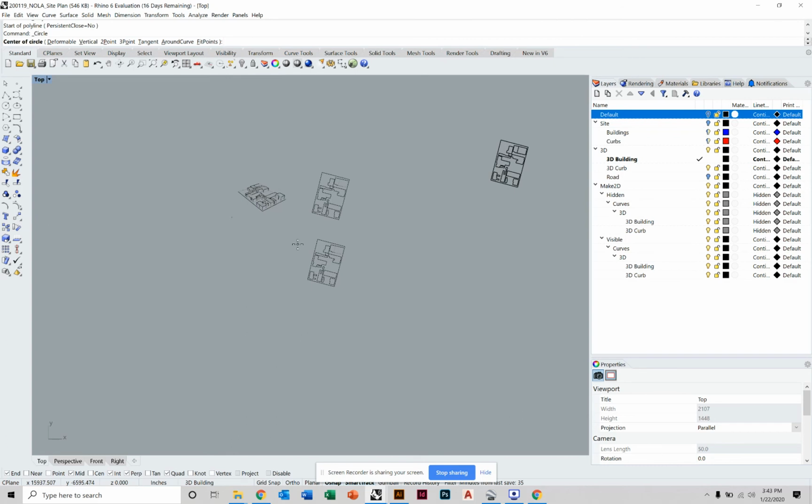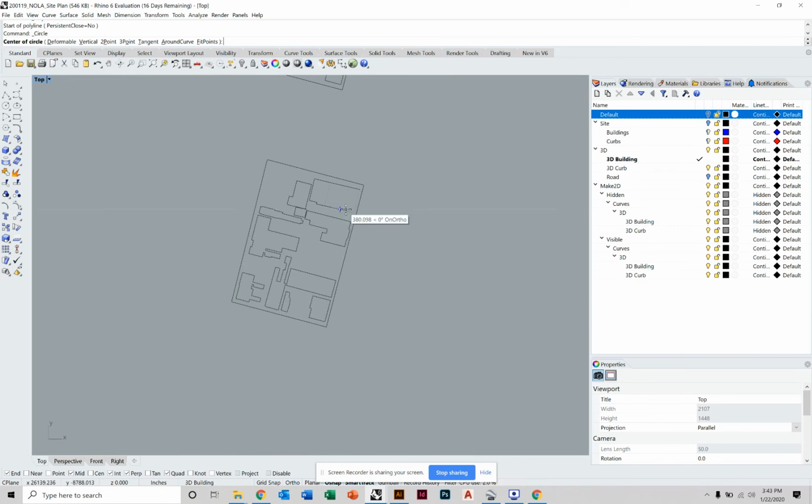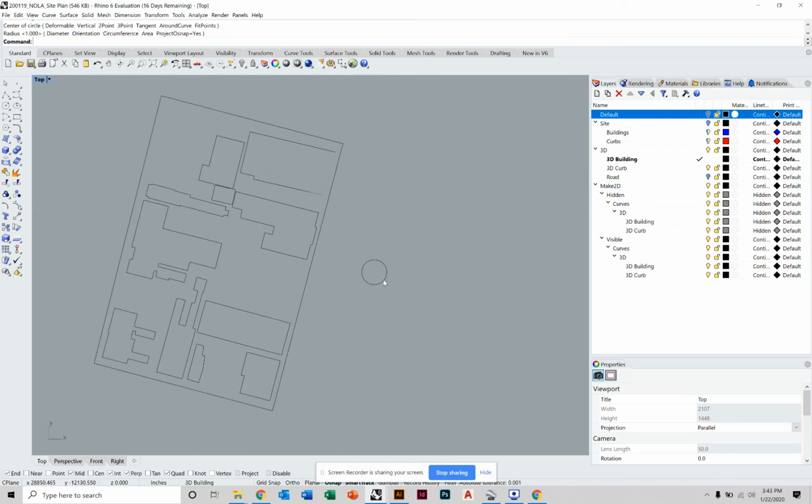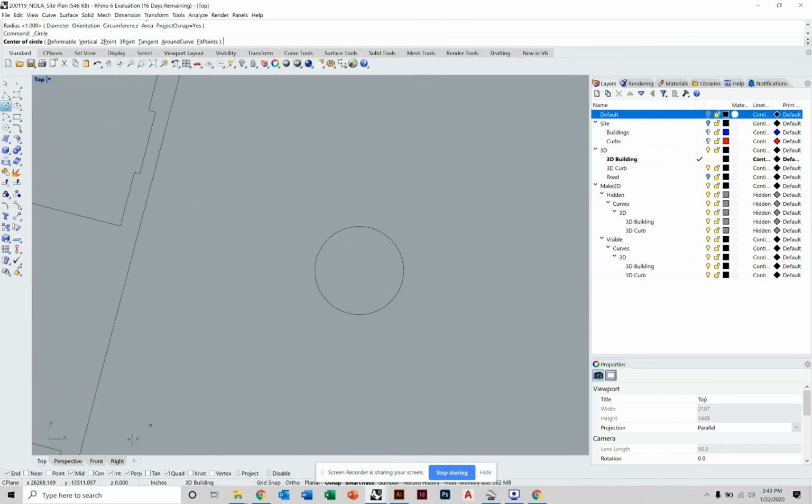I'm basically going to do this as an exercise to get you guys to learn how to scale. So I want to make sure that I hold on to true north. And true north should be north right now, which is why this is drawn at an angle. So what I'll do is I'll set a little indicator. I drew a circle. I clicked down here at center, and as you go to the edge of the circle, if you have your center snap on, it'll snap to the center. And I'm going to go straight vertical.